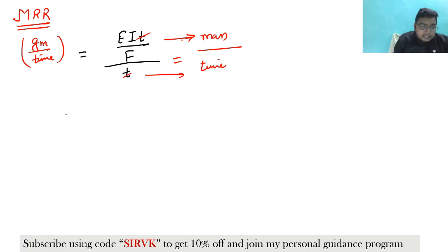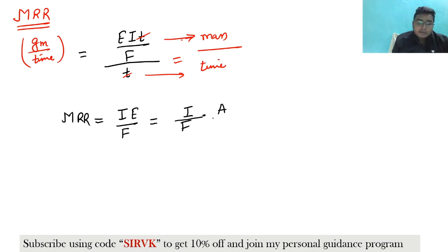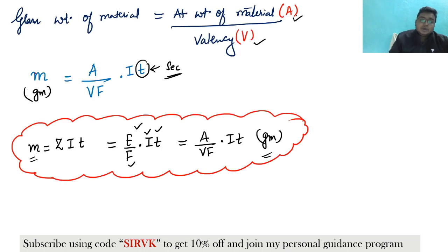So what I can say is that MRR is equal to IE by F, which is again written as I by F into E. And what is E? E is A by V, that is the atomic weight of the material divided by the valency.